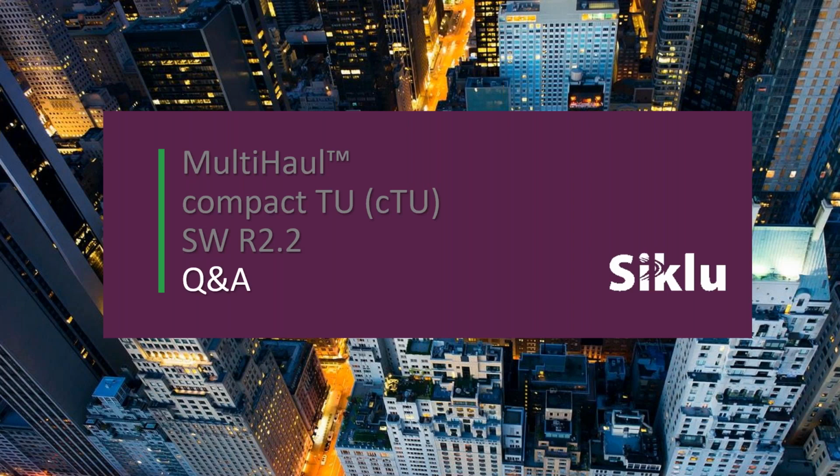No, I have here a question on alignment. So it is true that with traditional millimeter wave or microwave, because the antenna gain is relatively high, the aperture of the antennas is generally very small. A traditional 1-foot dish for millimeter wave has just a 1 degree aperture. The 2-foot dishes have even smaller aperture, half a degree. So yes, the alignment must be very precise.